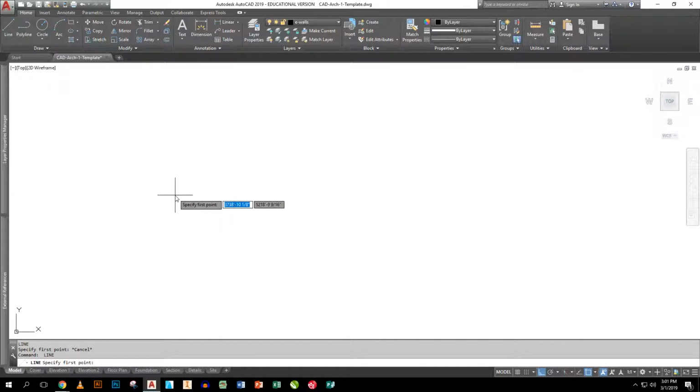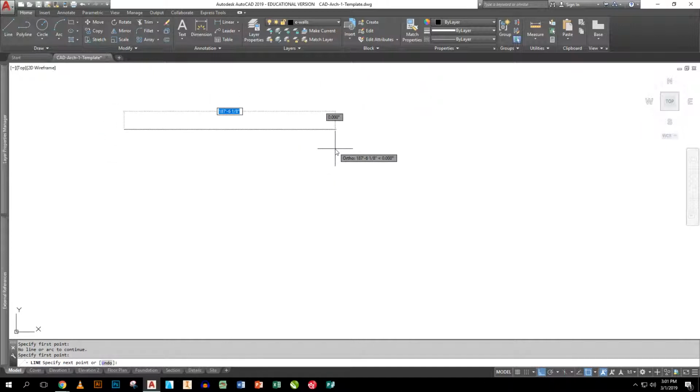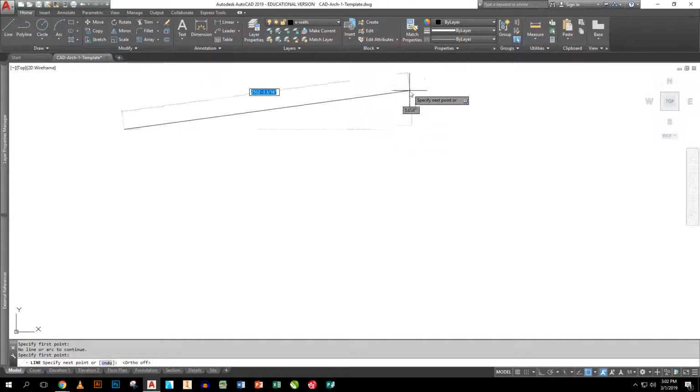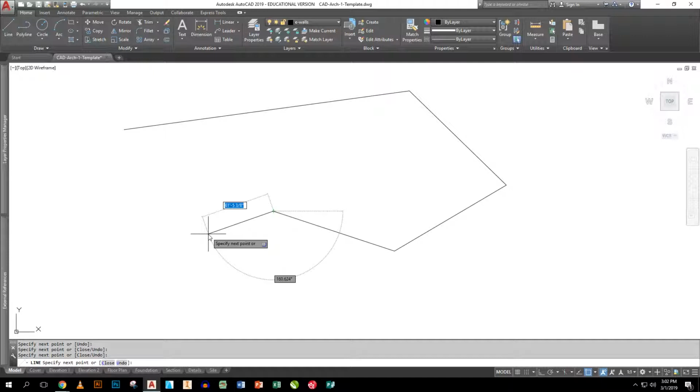And if I hit it again, it'll actually snap back to wherever the last line it was that I ended. See, so if I had drawn lines, like if I go like this and draw a line, I've got my ortho lock on. I'm going to turn it off by pushing my F8 key. If I draw a couple lines, and I hit my space bar, I cancel the line I'm in. If I hit it again, it goes back to line. I hit it a third time, it attaches to where I was.